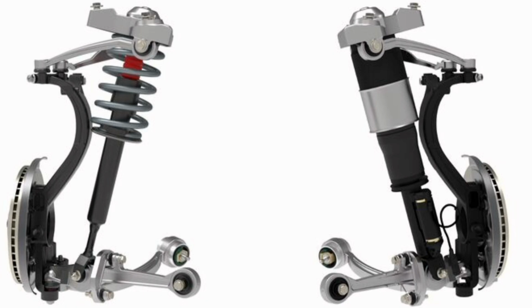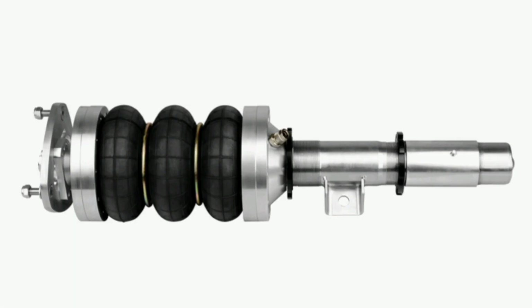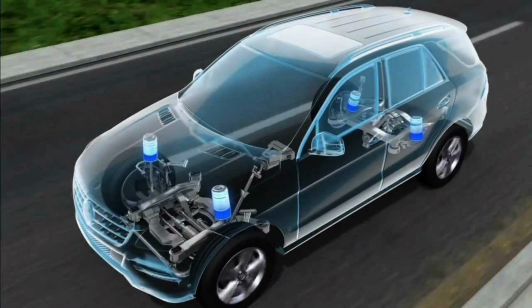The main components of an air suspension system are: 1. Airbags. They are the compressed air chambers that support the weight of the vehicle and absorb impacts. 2. Air compressor. It is the component in charge of generating compressed air for the pneumatic system. 3. Air tank. Stores the compressed air supplied by the compressor for later use. 4. Control valves. Regulate airflow to and from the airbags, allowing suspension height and stiffness to be adjusted.